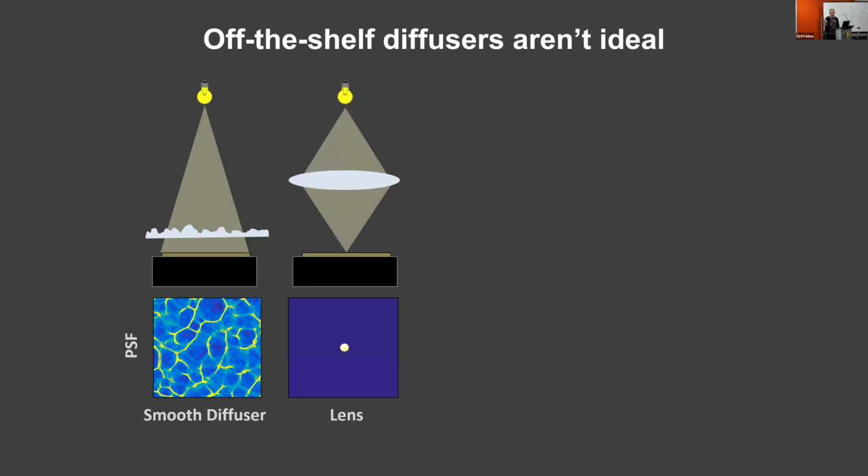Okay, so you can go to a regular camera and get a really nice focus spot. This is actually the best you can do SNR-wise. If you're designing an imaging system, if you don't care about compactness and you don't care about 3D, just a regular sharp PSF is the best you can do SNR-wise because it's Poisson noise. But if you're doing 3D, then this point spread function blurs out very quickly as you go off focus, and so that starts to be really difficult to deconvolve.